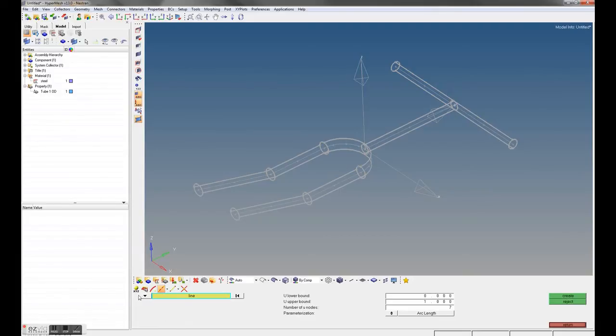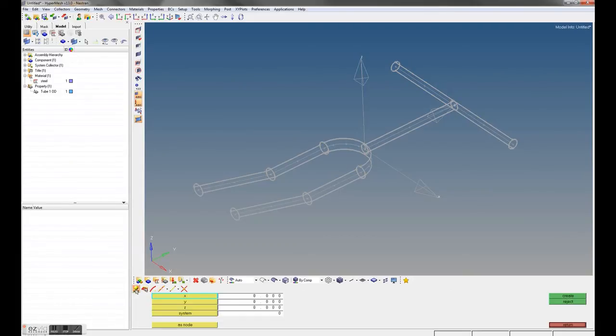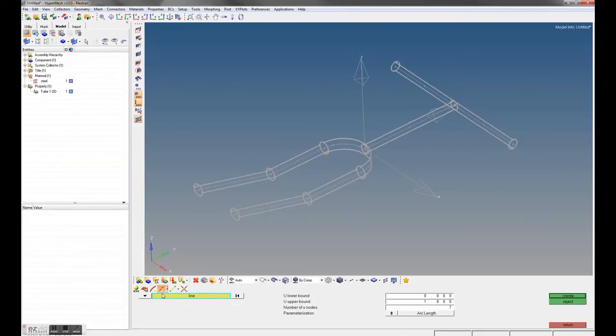And then there's lots of ways of creating nodes. You can put in coordinates. You can put them on points. Actually, I've never done that. I wonder if I can put them right on points. Doesn't, okay. You can put them at the center of circles, in between points, intersections of lines. But for us, the easiest one is this one right in the middle, which puts several nodes on an entity like a line. So either lines or surfaces. So we're going to use lines.